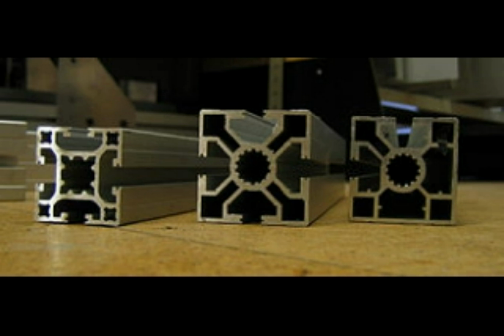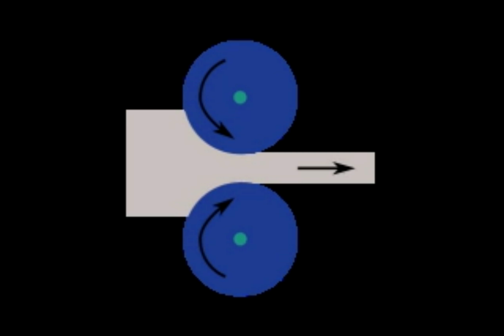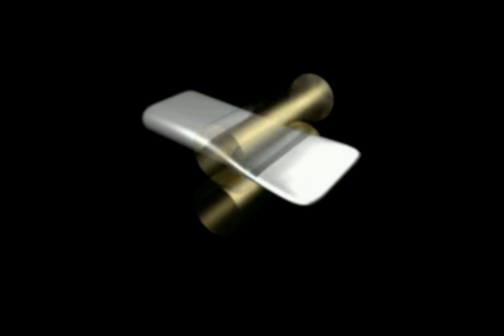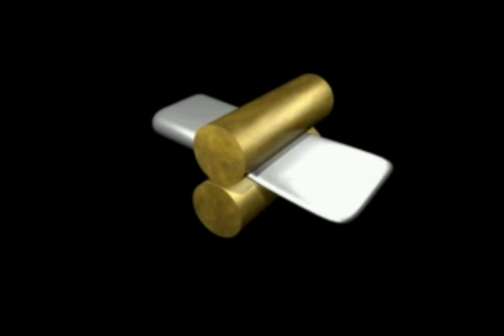Extrusion is the process of forcing a heated material, usually glass or metal, through a die mold to attain a specific cross-sectional shape, which can be very precise and have a high-grade surface finish. Rolling is when a metal is forced between one or more pairs of rollers to reduce thickness, which can be done at high and low temperatures. This is an inexpensive and quick process.